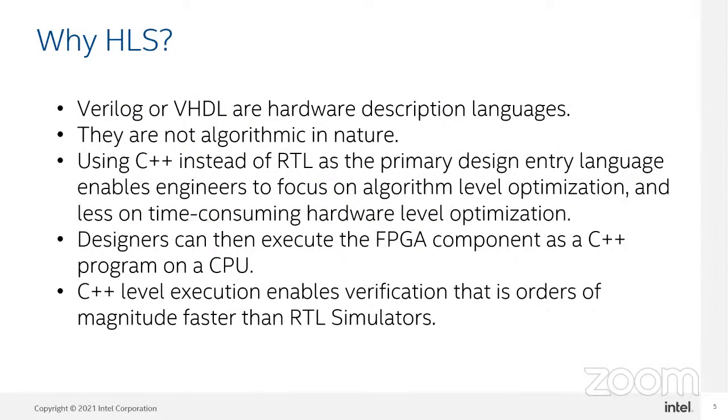Why high level synthesis? This is very, very important for us. Why HLS? Verilog and VHDL are hardware description languages, they are not algorithmic in nature. Using C++ instead of RTL as the primary design entry language enables engineers to focus on algorithmic level optimization.